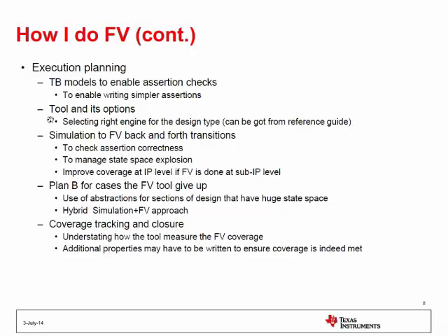It's not just the assertion, it's also the assertion correctness, because usually when you're moving from simulation to formal, one bigger wall that you will face is, in simulation I can look at the waveforms, I know how it is progressing, you will see things going around smoothly. But when you go to formal, it says yes or no, but you don't have the feel of what exactly is happening, am I doing the right thing? You still have those doubts in your mind.